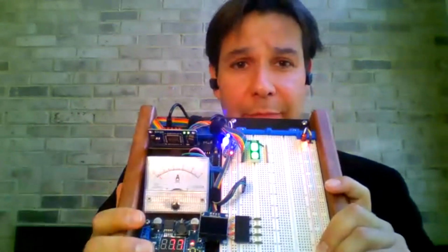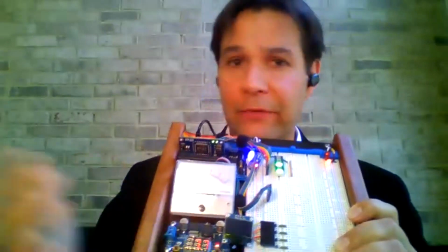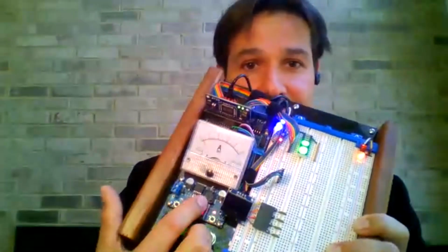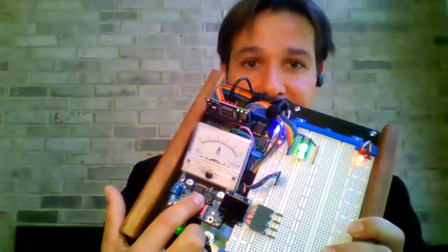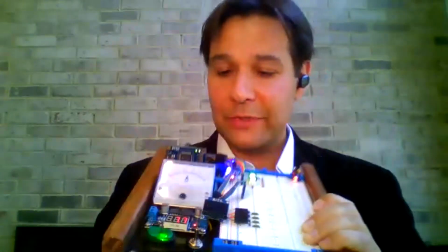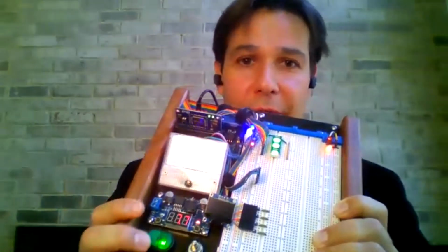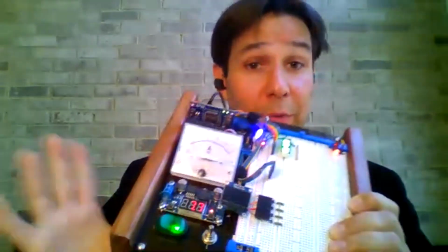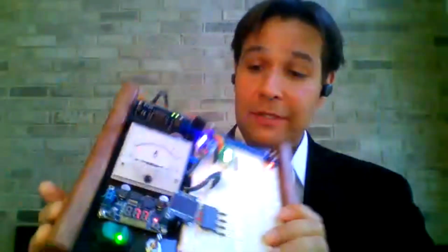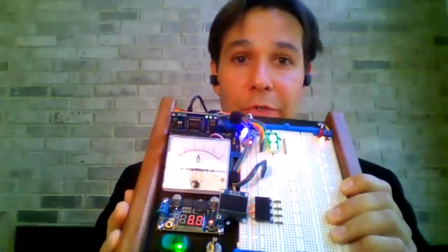I haven't had time to fully debug what was wrong with this, but I think one of the problems I had, because I really tested the heck out of my prototype, but then for the mass production, I got cute and decided I was going to hot glue the wires down to keep them from breaking off. But I think that extra heat messed up the switching mode chip, and these actually can't start up under any kind of a load or it causes a problem. So I'll work out those bugs for the final iteration that we create, but it's just kind of nice to be able to have instant variable power supply for super cheap.